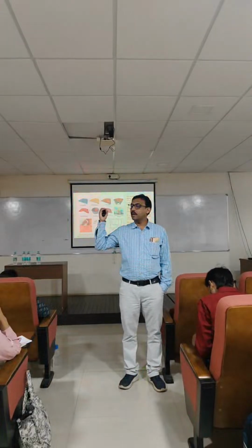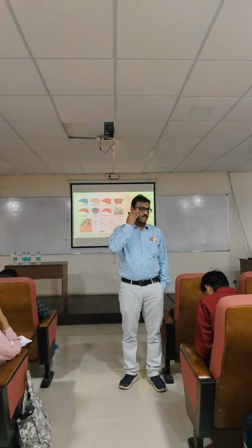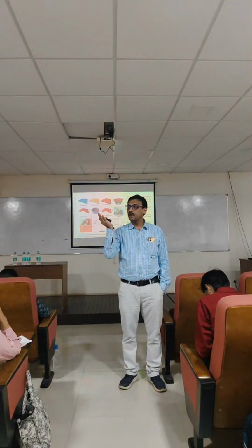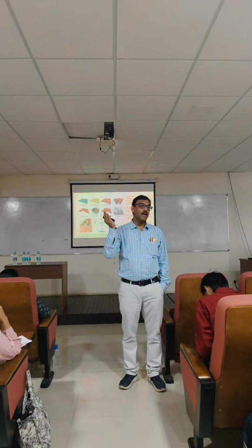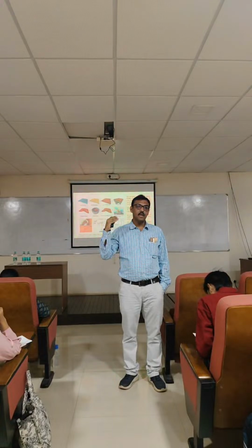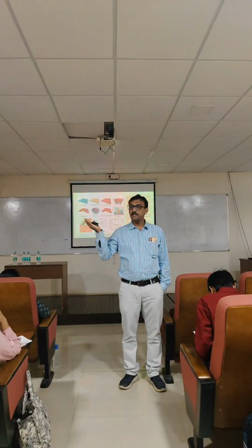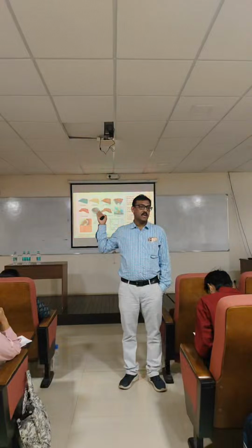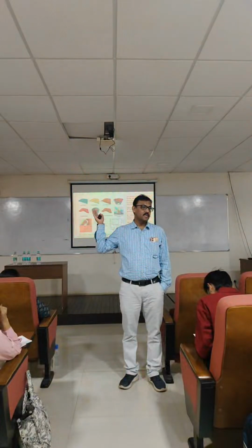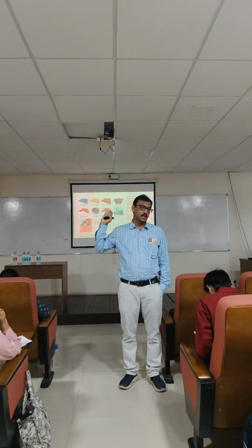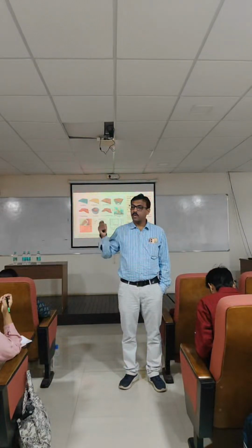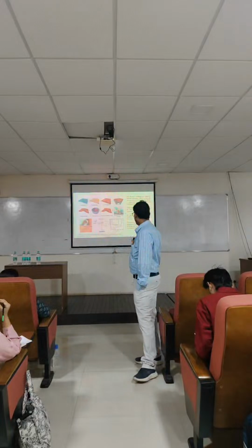What is the analyte here? The tear, and in the tear there is glucose. What are we monitoring? We are monitoring the transistor signal, and that is the transduction system. So we have the receptor here, indium oxide, the analyte is the tear, and the transduction system is the transistor. We can get the signal out of here.